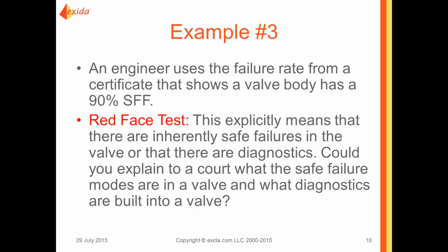Obviously, except in the very rare case when the safe state is fail open, there's not a safe failure mode for a valve that needs to close on trip, and in a valve body there absolutely are no built-in diagnostics.